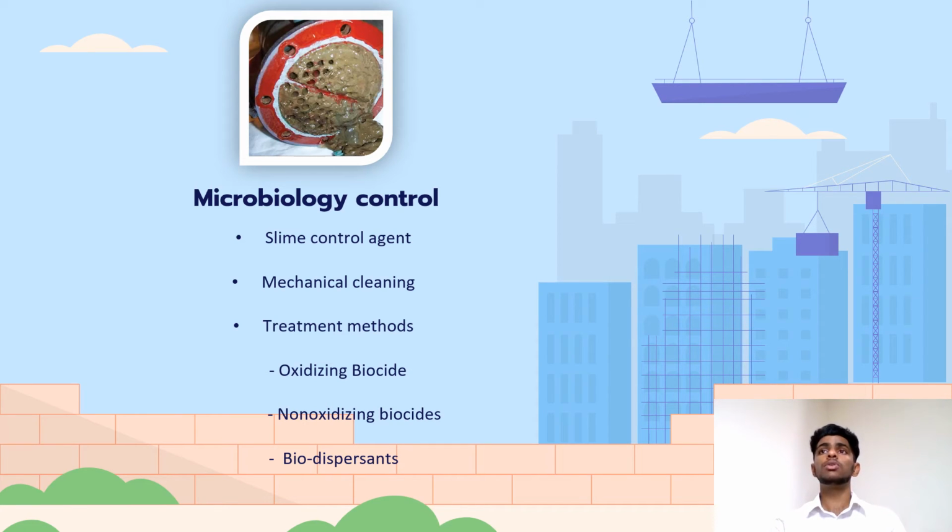Oxidizing biocides include those chemicals that have the ability to kill microorganisms through an electrochemical process of oxidation. The oxidizing agents such as chlorine gas exchange electrons in the process while the substance becoming oxidized loses control. Some oxidizing biocides used are chlorine, bromine, iodine, chlorine dioxide, and ozone.